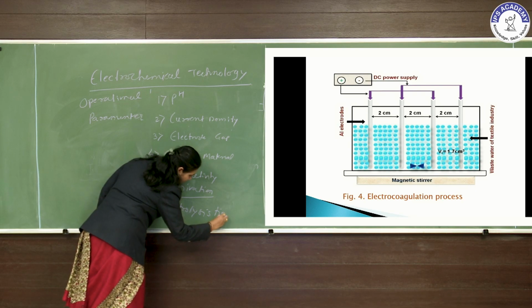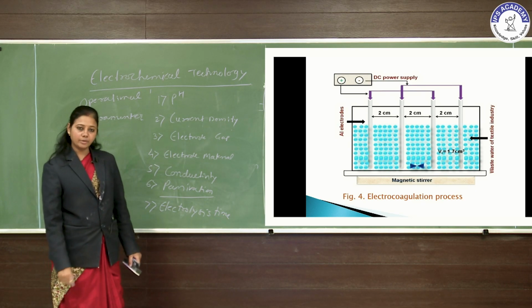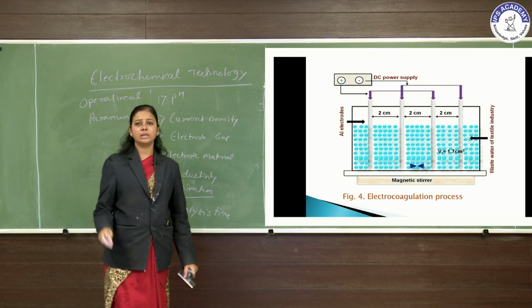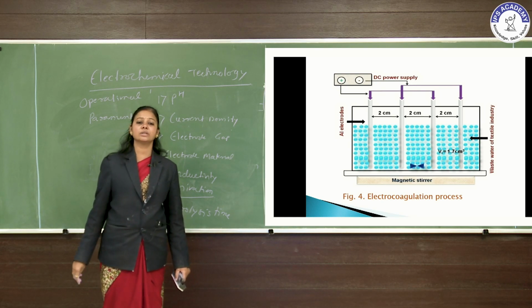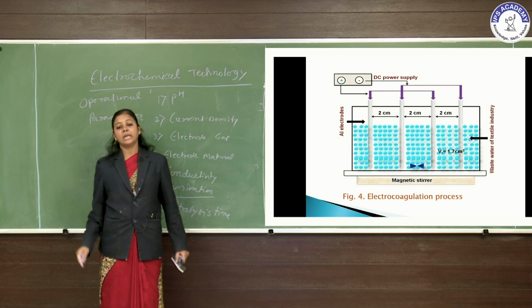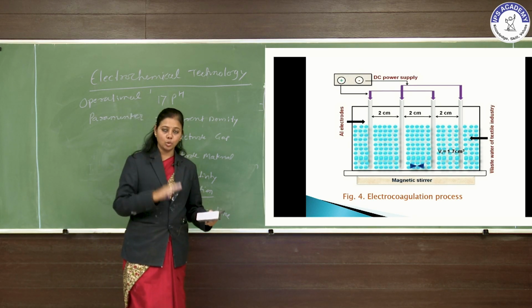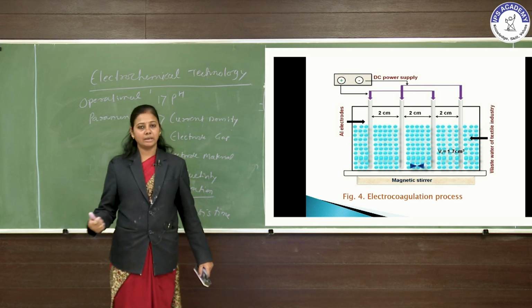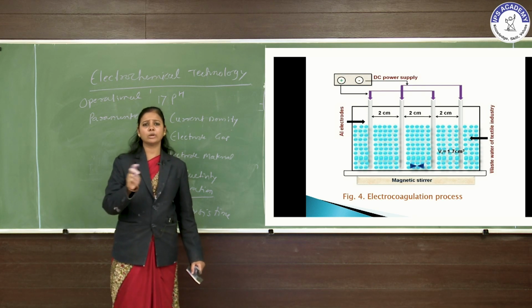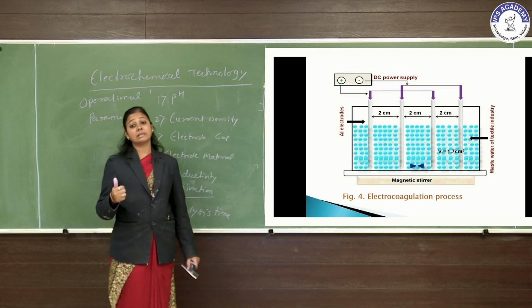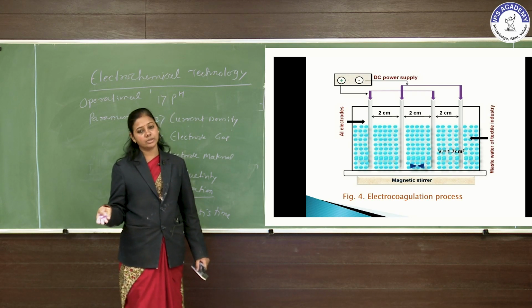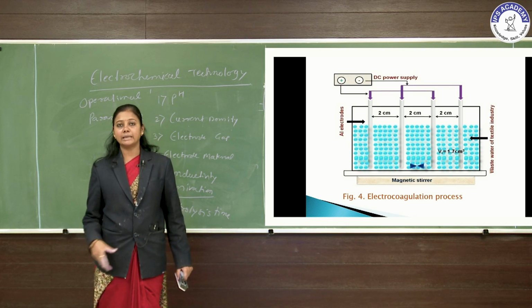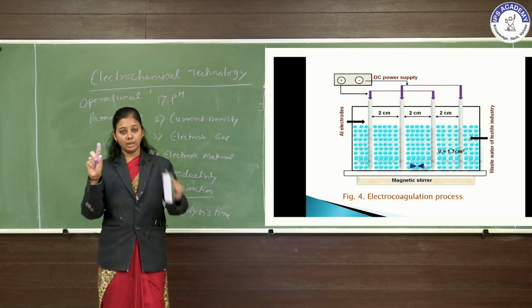Electrolysis time is again a very important parameter. The minimum time of this electrocoagulation unit is 100 to 120 minutes. It is sufficient to treat that particular wastewater. If we increase the electrolysis time, we cannot alter the efficiency; ultimately, we only increase the cost of the electrocoagulation system. So, electrolysis time is again taken into consideration while designing the electrocoagulation unit for that particular wastewater system.